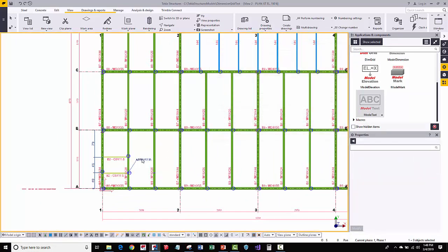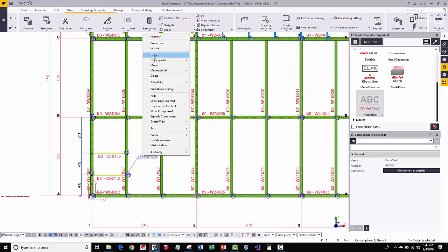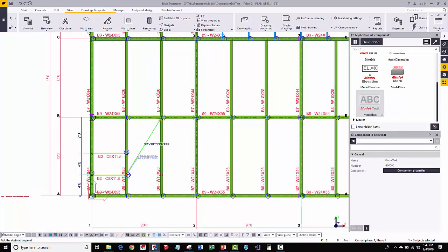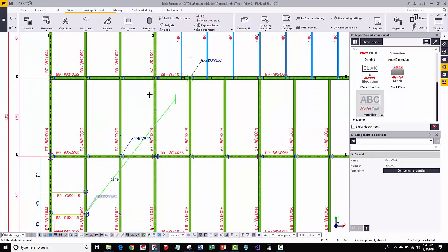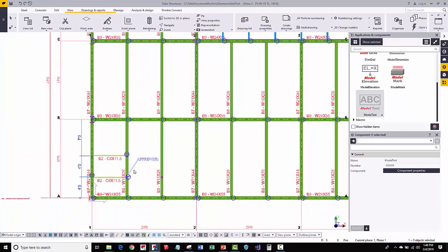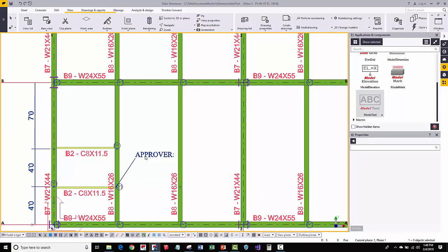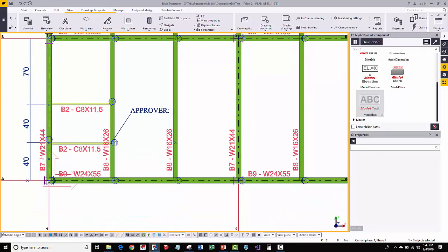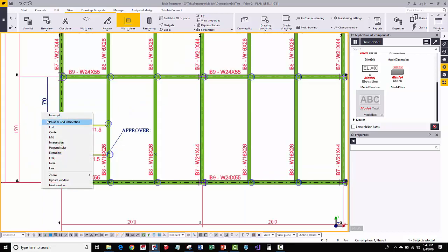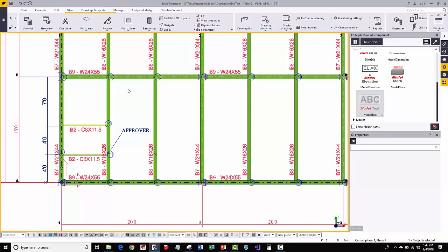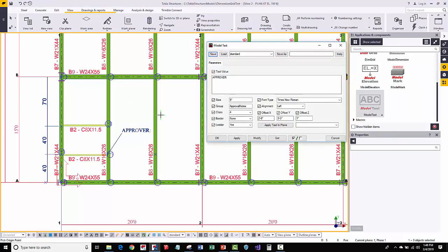Before this update, you could have just put in one note here, and then you could have just done a copy. So if you're doing a whole bunch of markups on the same kind of plane, you can easily copy existing ones and then come back and modify them. But just in case you wanted to put these in more quickly, if you change your work plane, I'm going to use the work plane tool here. I changed the work plane to either the view or this current plan because I'm in a 2D floor plan elevation here.